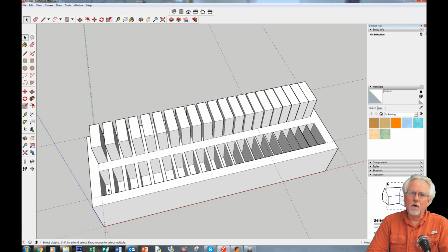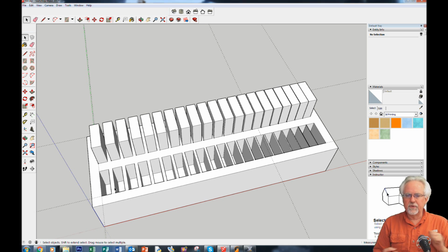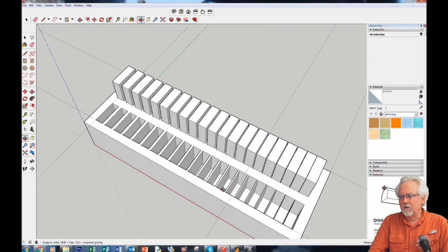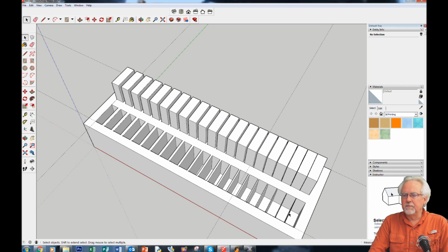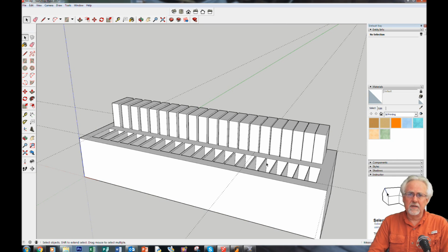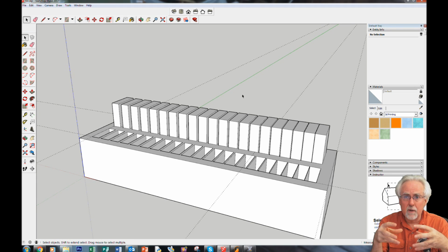Similarly, on the holes over here, I'm going to start with the holes 2 millimeters apart, go all the way out to where my holes are 0.1 millimeter apart, and then see where things break. When I design this and then make it, I will have my first initial set of design rules. This is also just a great opportunity for us to sharpen our design skills in SketchUp.